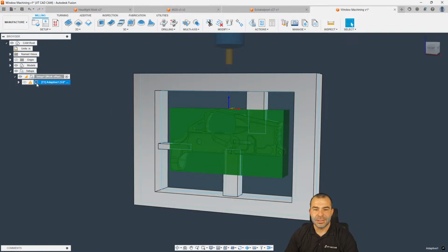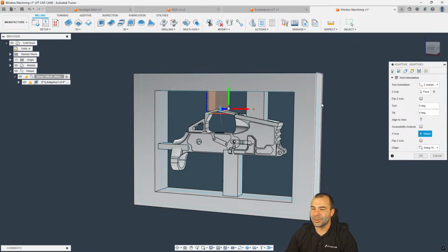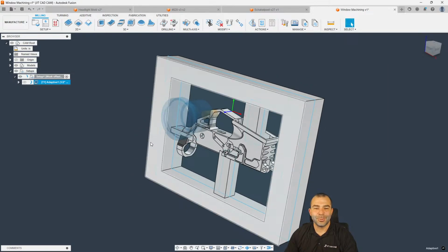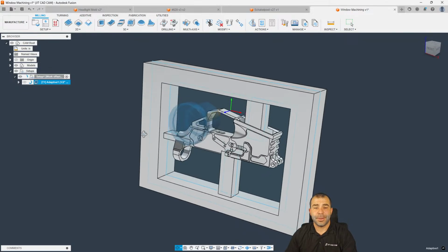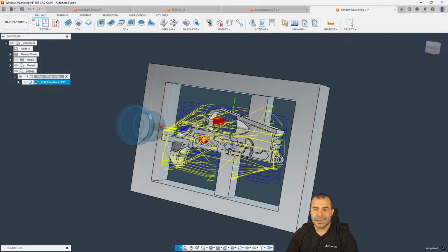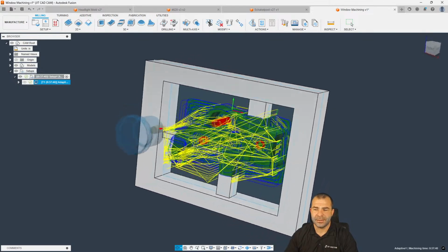Now, keep in mind, my tool is pointed the wrong way because yours truly is moving a little quick here and we're trying to get a very quick result. But as you can see, we'll do our machining horizontally. And because of our jig and fixture avoidance, we should see that populate through in that toolpath. Now, keep in mind, my stock is currently turned on, so we need to go back and redefine my stock. That's why we're seeing a small toolpath for machining.